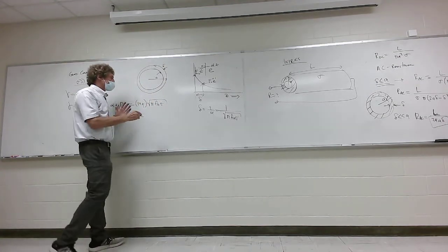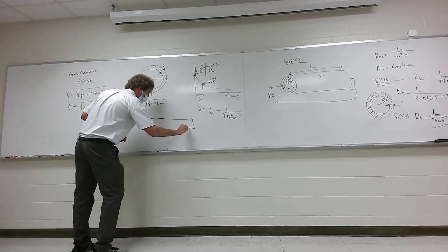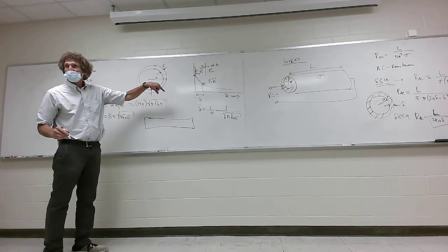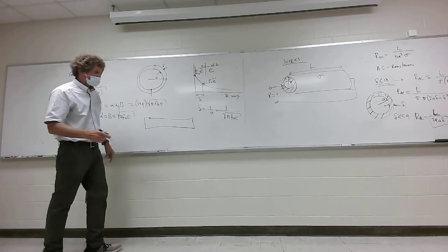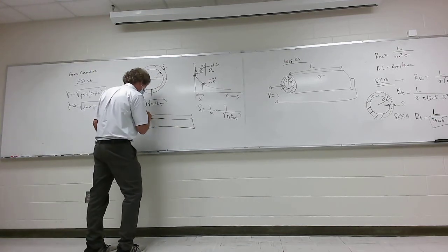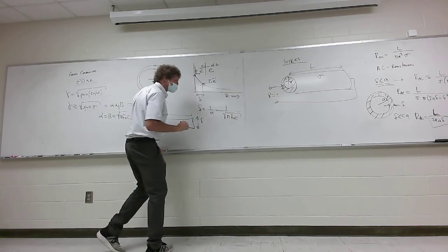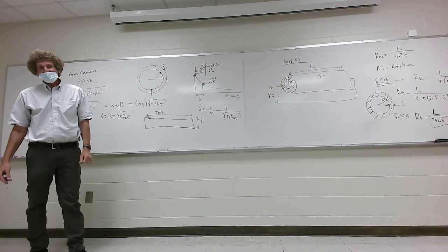Now take that, cut it right here, and just peel it into one long piece. All right, what's the circumference of a circle? 2 pi times the radius, right? Or the perimeter or circumference. So this dimension would be 2 pi A, and the thickness would be this, and now that is the area the current has to go through. Y'all follow me? That's the AC resistance.